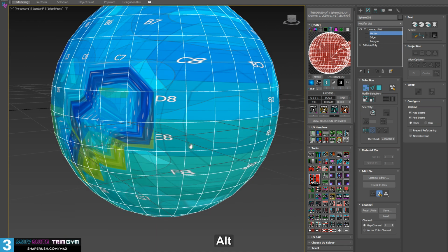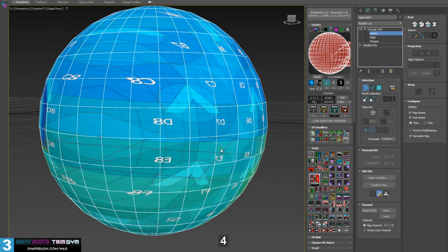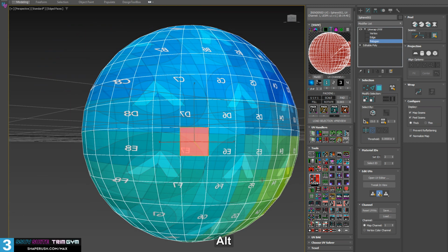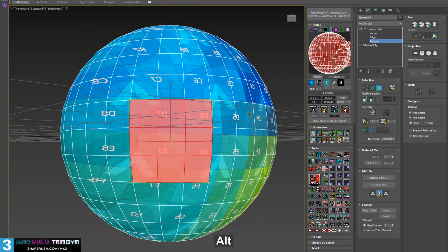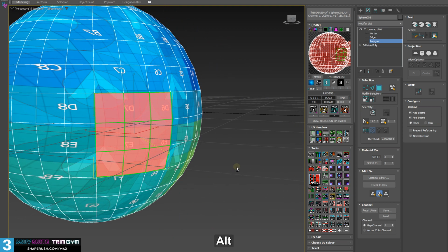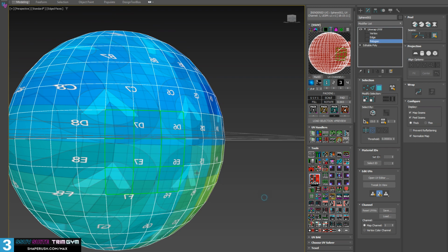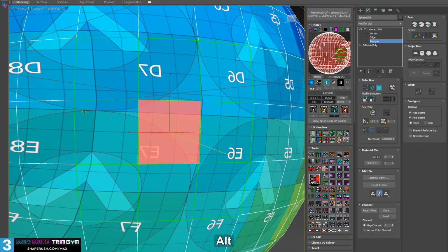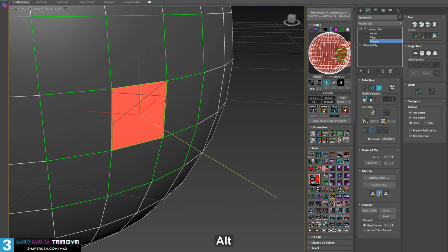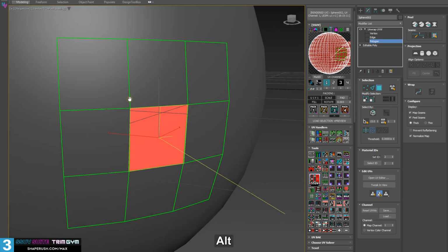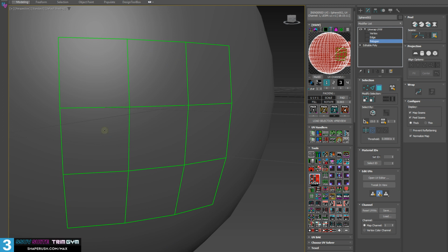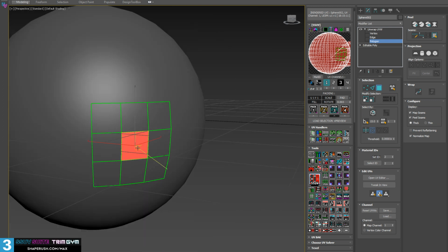Close that out. Stitch is next. Let's select some faces. I'm going to increase this and right click to break. I think I clicked the tooltip accidentally. All right, so there we are. Now I want to stitch this face back into these other faces. Okay, let's get into this so it's easier to see. We have 9 faces that are 9 elements.